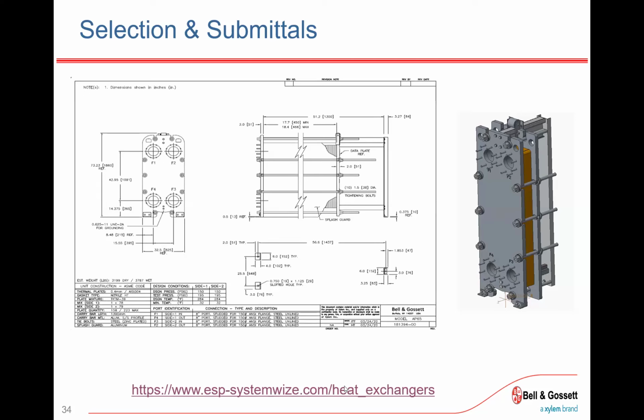So if you had a relief valve setting on a non-potable, like a boiler circuit, at a 75-pound relief valve, but then you've got 60 PSI coming in on your street, if there was any leak you could cross-contaminate. So to my understanding, it matters if the non-potable system pressures, or the relief valve, were greater than the operating pressure of the other side.